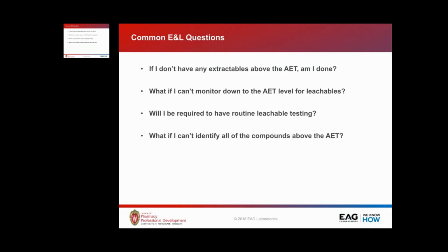In those cases, what we typically recommend is to go back and characterize the extractables. Go up a level, identify all of your extractable peaks that do correlate down to it, and use that as your worst case scenario. And we've seen that be successful multiple times.